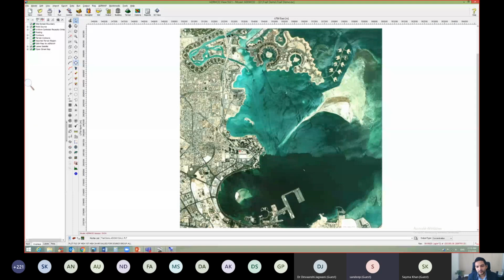I can see on the internet there are software like BREEZE software or Envirotrans, I think, Envirovare and all this. These are the consultancies. Correct, but these are the detailed software, but there are open software available from Lakes Environments. You can visit the Lakes Environments website, where you can download the freeware, open software tools, which are screening models. You can download SCREEN3. You can also download WRPLOT, which is a freeware for generating wind roses using meteorological data. So for training, this is freely available from Lakes Environments only. Okay, sir. Thank you.